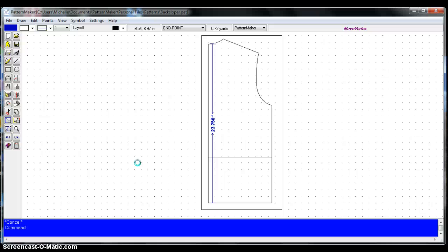Let's create some text. Select the text icon. It looks like a larger letter A in fancy script right over here. A text object has only one vertex. It shows where the lower left corner of the text goes. Your first text object will be a label for the sloper object. So select a point about 1.5 inches below the lower left corner of the sloper.